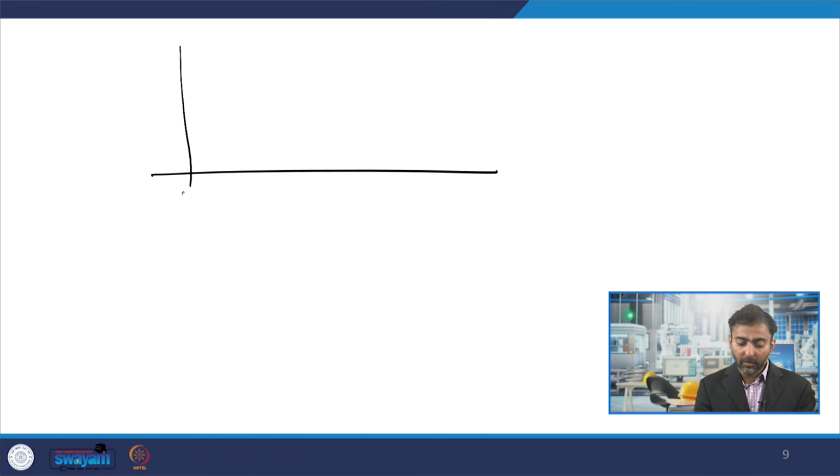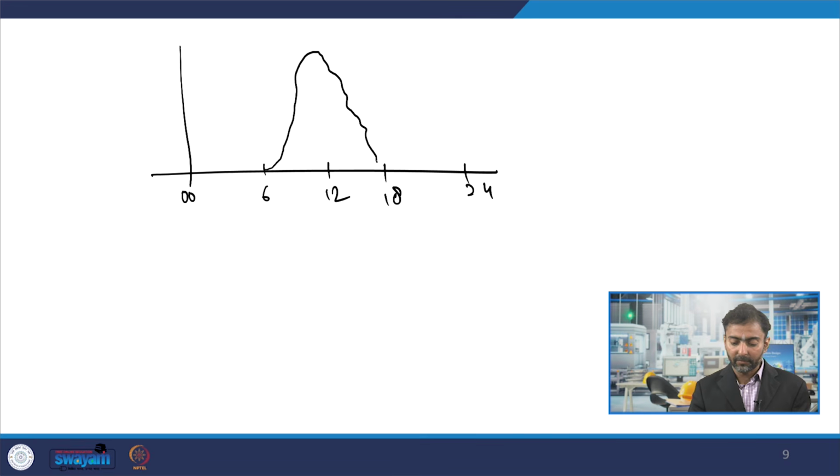So if you look at the period of a day, let us say from 00 hours to 2400 hours, with 12 hours here and 6 and 18, and if I were to plot the electricity generation from any solar PV plant, maybe around 6-7 am when the sun rises, it gradually picks up, goes up, peaks around 12 noon or 1, and then again gradually comes down, and by 5 or 6 pm it is down to 0 again. So my installed capacity is only running, out of the overall 24 hours, hardly 8 to 10 hours properly, and that too it is peaking only maybe around 2 to 3 hours in the afternoon, around the midday time.